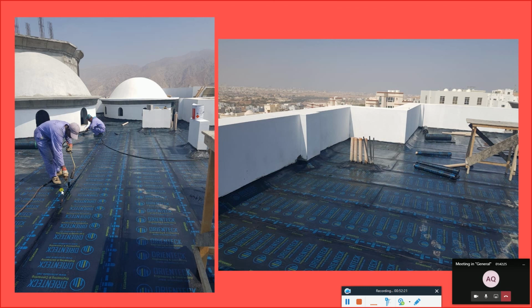Small areas, the water will be penetrating inside the concrete slab, and then it will go for the steel, especially old houses. It will penetrate into the concrete. It will attack the reinforcement, and after a certain period you will see that certain particular areas of the roof are bending because the steel is not doing its job, since it's already corroded. So this is a very important thing we need to tackle by using proper waterproofing.